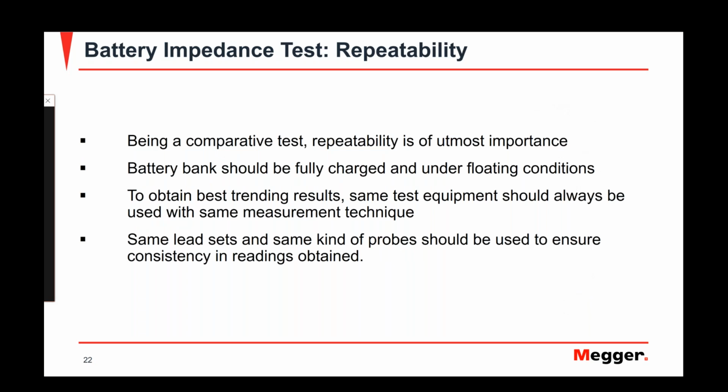Test repeatability is really important whenever we do these tests. The values that we get, like I said before, are compared, so being able to produce consistent results is really important. The way that we do this is by having proper testing techniques and by applying the same procedures to the battery every time.